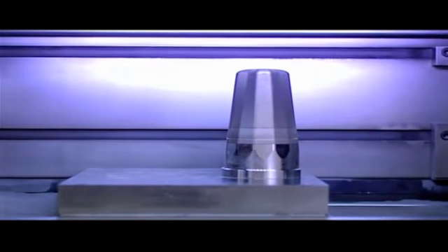This is then a fully melted metal or plastic component that can be used in aerospace and consumer products, and we're going to be showing a wide range of applications for this manufacturing technique during this presentation. So here it is. This is a tool insert for a cup, actually, with conformal cooling channels on the inside. So going back to the reasons behind why we would even think about 3D printing.